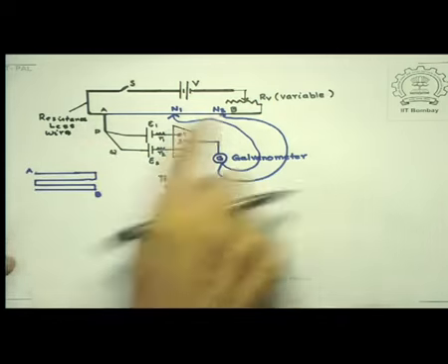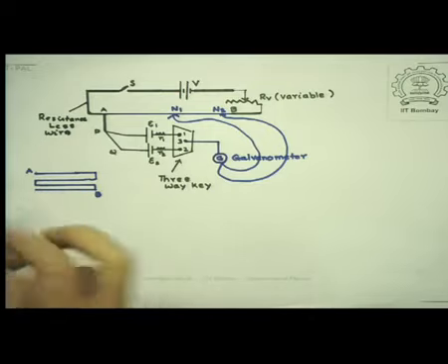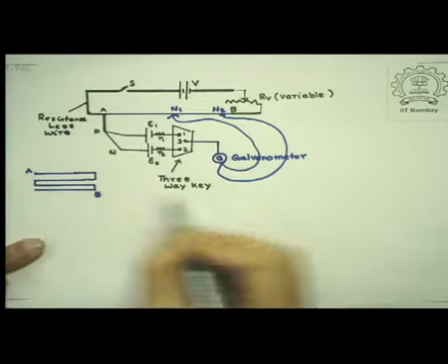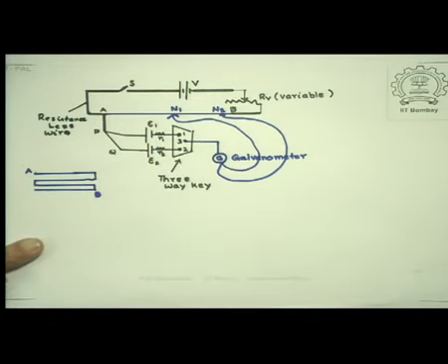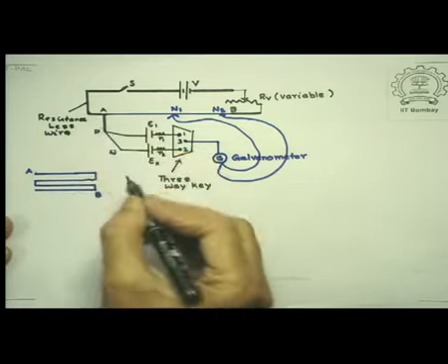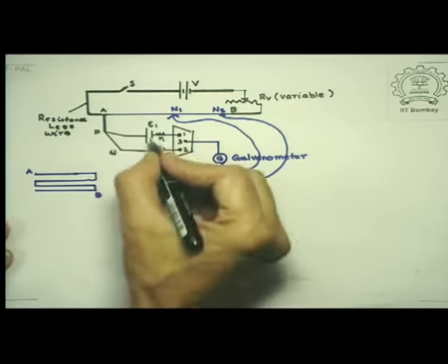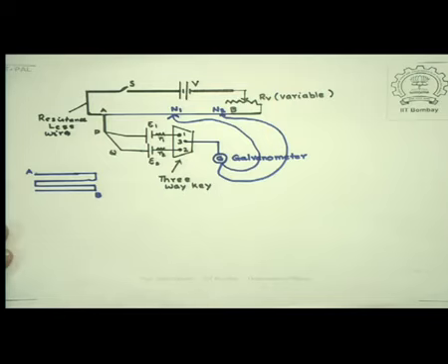So between the points A and B is a long uniform wire which usually has several turns as is shown here, but for convenience I have simply put it stretched between the points A and B of the circuit. Now the point A is connected to the two sources of EMFs which we want to compare.